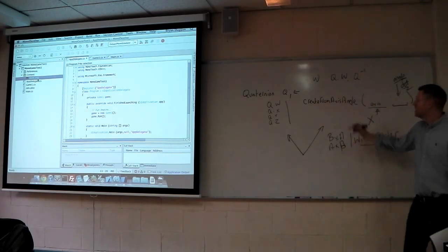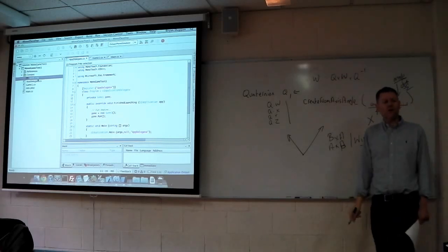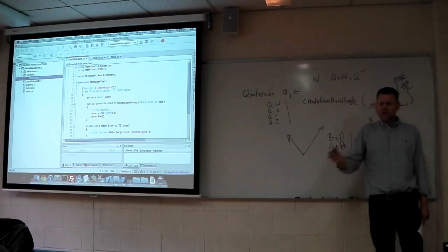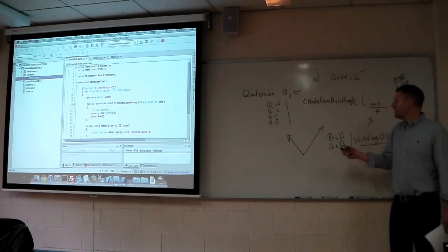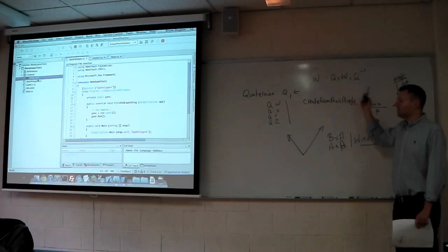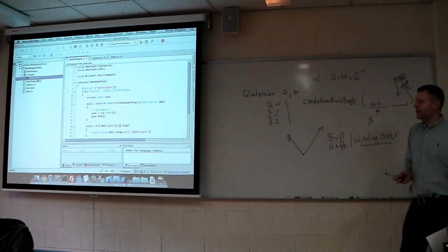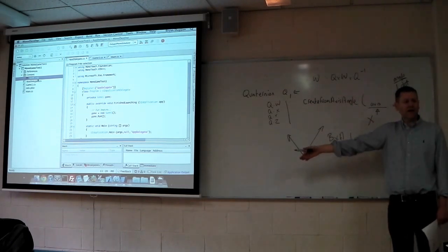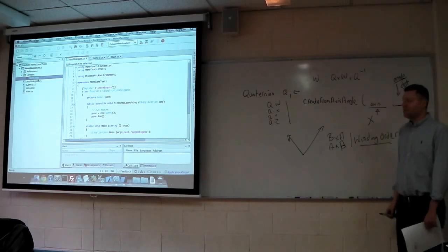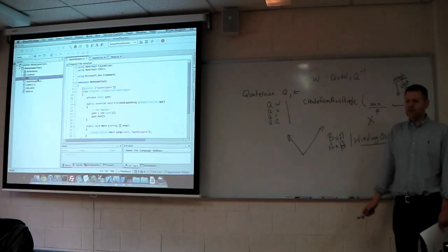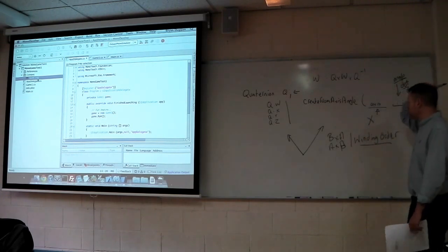So that's the equation, and sorry, that should really be multiplied by, to distinguish between the dot product. These are the cross product of two quaternions. I don't know if there's a dot product of two quaternions defined, to be honest. The thing is, when we're talking about multiplying, in this particular context, we're talking about the cross product of two quaternions. The cross product of two quaternions takes about half a page, or at least one big full screen, to write out how you calculate it. It's just a whole load of addition and subtraction and multiplication of the elements of the two quaternions. But you never need to know it. You use the multiplication operator overloaded, of the quaternions in order to do it.